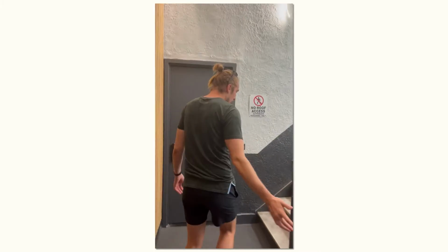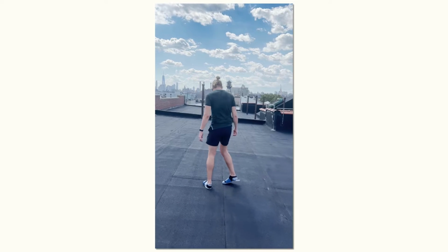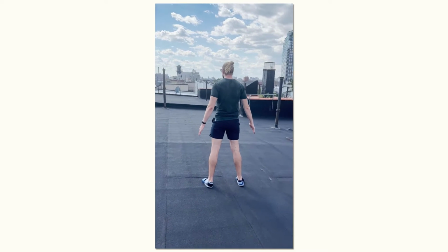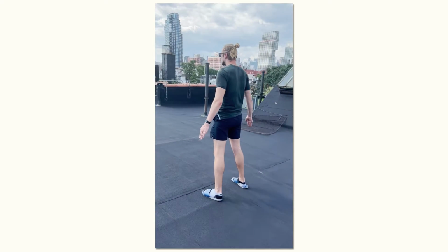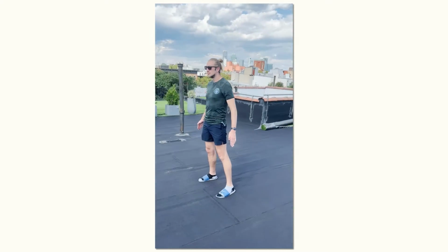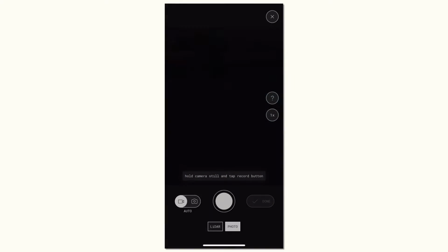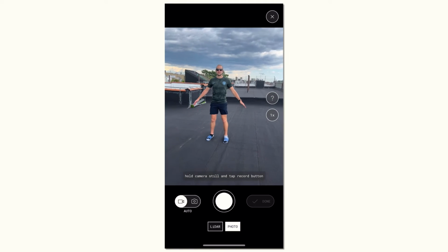When taking a good quality human scan, make sure to find a space with lots of light. Once you've found a good spot, have your friend stand in A pose. This is where your arms are slightly outstretched from your torso, fingers all touch together, feet slightly more than shoulder width apart. Then we'll open Polycam and get into the photo mode.